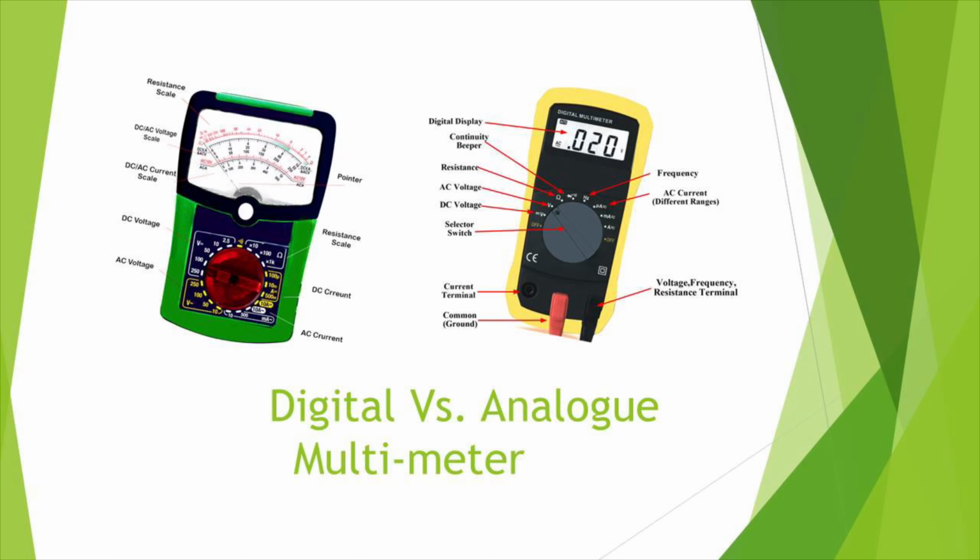The DMM is capable of measuring AC and DC voltage, AC and DC current, resistance, conductance, and decibels. Often a DMM has more features than an analog meter, such as frequency, capacitance, inductance, temperature, and transistor current gain. The input impedance is also very high and has little effect on loading the circuit. Precise readings can be taken easily. A DMM uses a very fast analog to digital converter to sample the input signal and convert it to a readable format on the LCD display.